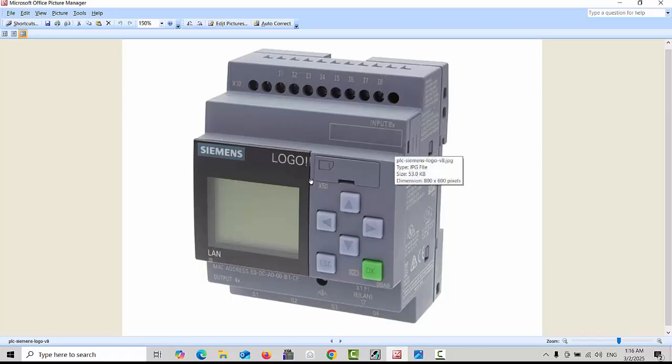You can see in this picture, this PLC has built-in 8 inputs, I1.0 up to 1.2, 1.3, 4, 5, 6 and 7. Total inputs are 8 inputs. And outputs start from Q1 and Q2, Q3 and Q4. In total, the CPU has only 4 outputs.